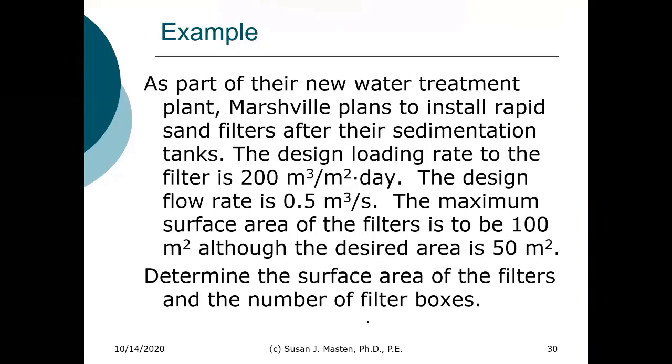So the question is, are the wash troughs serving the purpose of increasing the backwashing efficiency? The wash troughs are really capturing the water. As you're backwashing that filter, you need to be able to capture that water. And the wash troughs are basically your collection device.